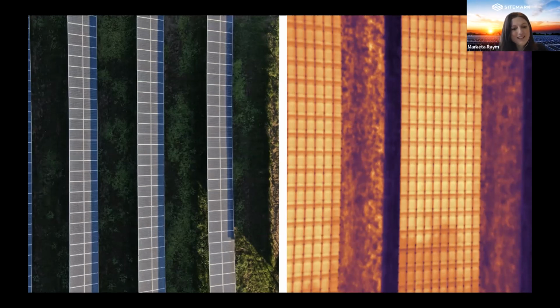Yeah, absolutely. This is the first really great example showing what happens when the inspection is flown in the winter. First off, winter is also a perfect time to fly the inspection, like summer, but the day isn't that long, so we are limited to a time window in the day. In winter the time can be something around noon, and we might get a maximum of 1 hour of good irradiance. Here we can see that the sun is really too low, and that has caused this self-shading of the panels.